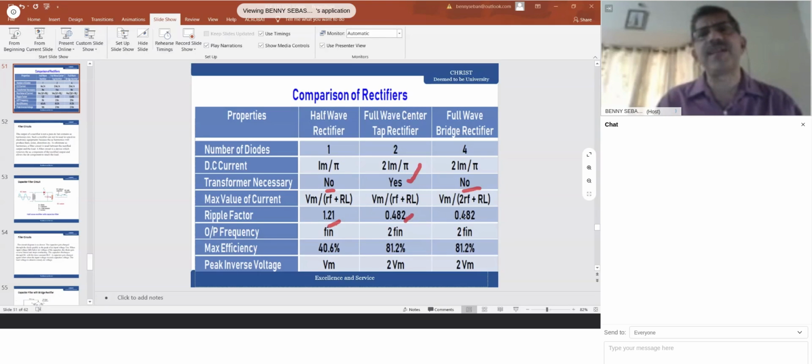So these two are better options when you think about a practical circuit. Ripple factor is basically the ratio of AC to DC. Our target is this: when you get a ratio of more than 1, the numerator is more, which means AC is still more. That is against what we wanted. We wanted more DC output than AC. Hope you have gone through these things.